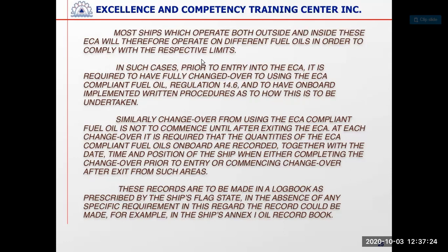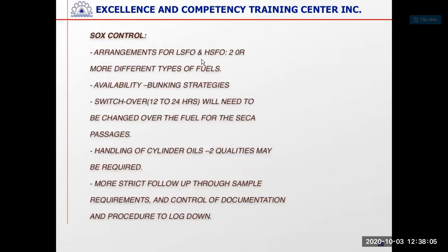So then you need to change over the fuel oil, and as per your ship design and equipment, it will take a long time. So before you enter into the ECA area, the changeover should be complete, and you need to have logged all the details of when and how you started your changeover, entry into ECA area, and your changeover completion time. Similarly, when you are coming out of ECA area, the changeover can start only when you are outside ECA area, and all the records have to be maintained in the logbook, or as per flag state requirement, the oil record book.